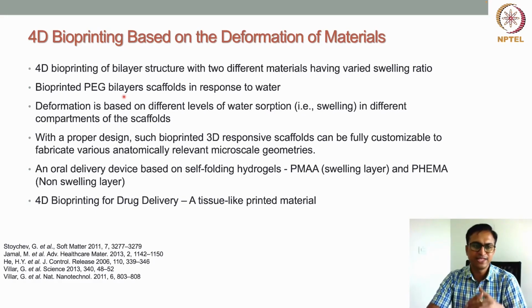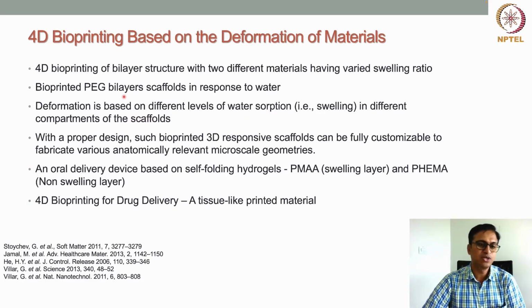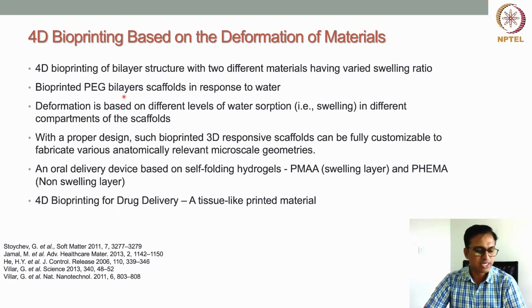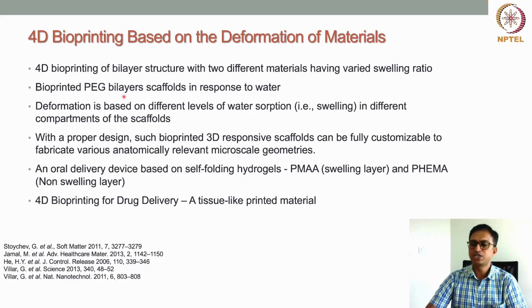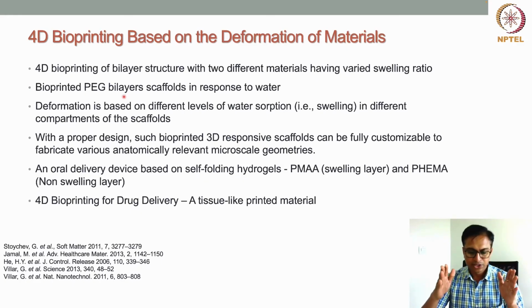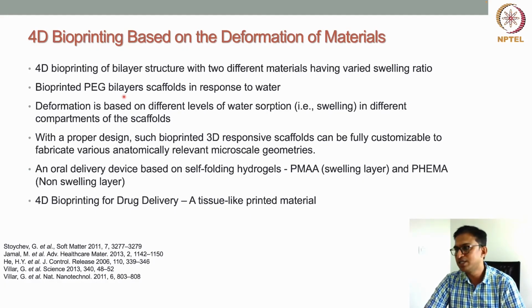Suppose you use PEGDA, a photo cross-linkable material. If we cross-link that material by inducing some light, then the material will be photo cross-linked. If we control the cross-link density, that means the cross-linking intensity within the structure, and generate two widely differing cross-link structures, then there will be different swelling ratios, and also bending if we introduce that to water.